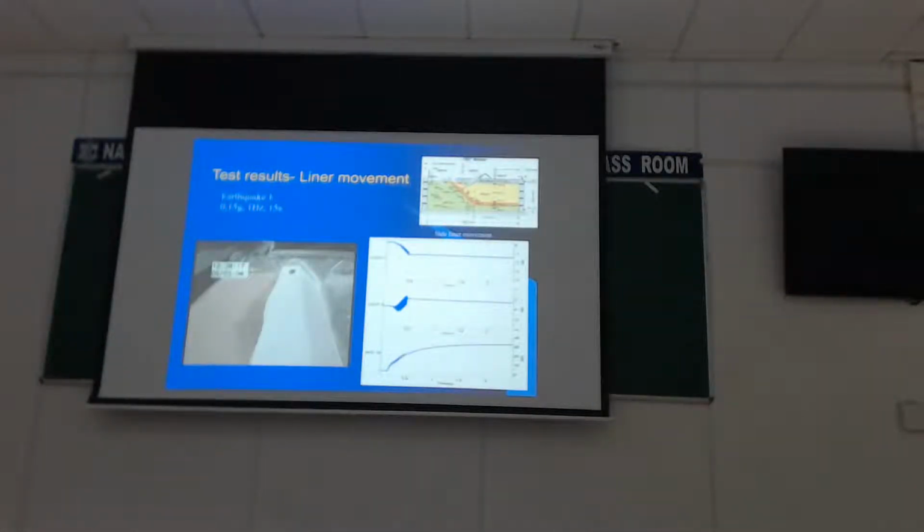So we could see from the LVDT measurements, this particular vertical settlement is actually showing a heave. So it's going up, while the one here is basically moving in. So that goes in, this goes up. It's almost like an undrained event where the volume has to stay constant. So if I push one end, the other end has to go up.